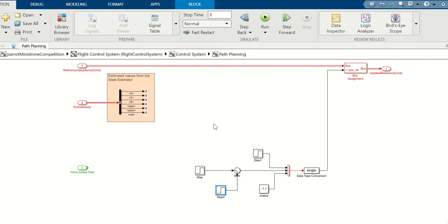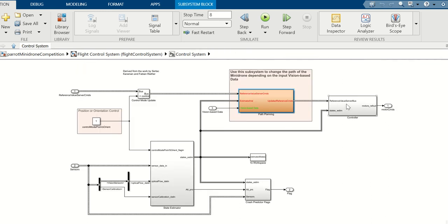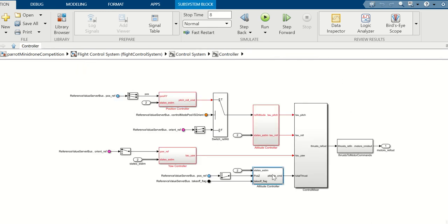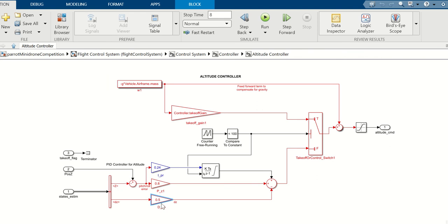Now be careful to make a note of your controller gains, because what I found is sometimes you change the controller gains, you change 2 or 3, and you forget what they were before, and when it runs, your new gains go unstable, and then you've forgotten what your gains are. So my recommendation would be to go over here somewhere, go into here, and go into these boxes and screen dump these, so you know what the numbers are.